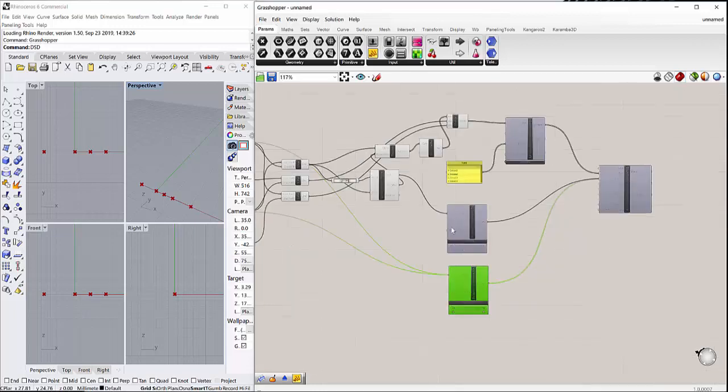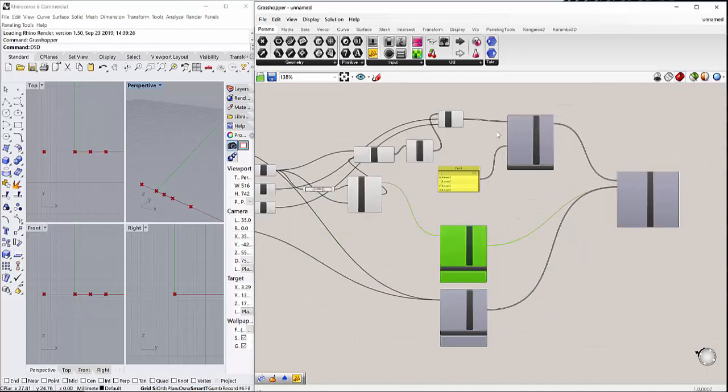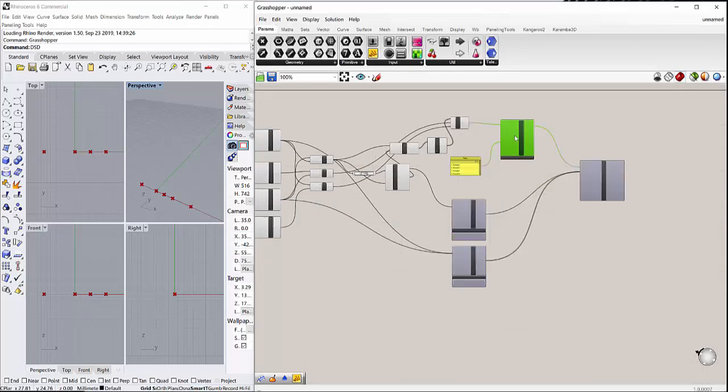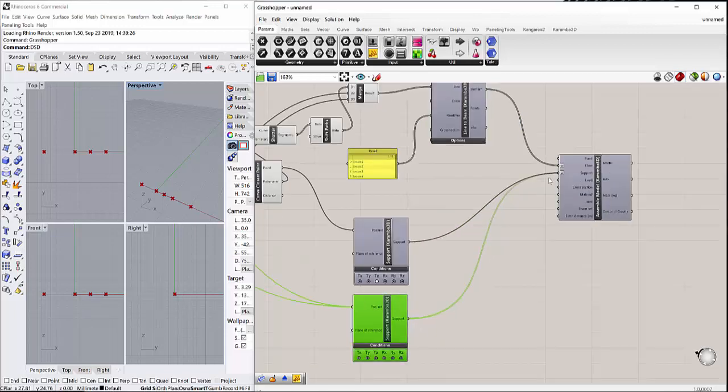So now I'm done with the supports. So I created a line to beam, I created the support for the beam, and now what I need to create is the load. So for creating load, I need to first define the type of load I want and on which point.